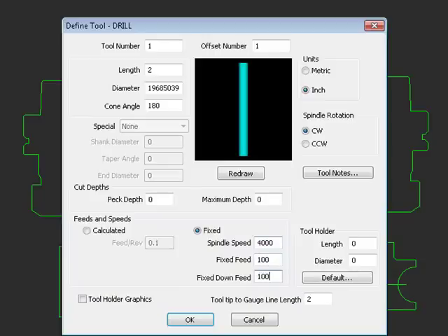And that's essentially it. You see, one of the clear advantages that you have with SEM machining centers is that you don't have to define multiple drill bits for the gang bore or for the line boring. Let's say that you have 22 different 5mm drill bits. You only need to define one bit for every different diameter that you have.